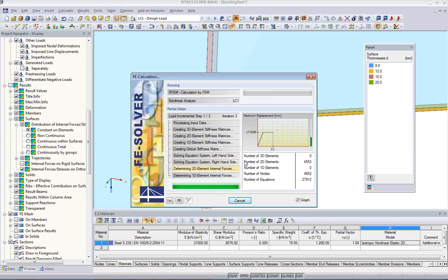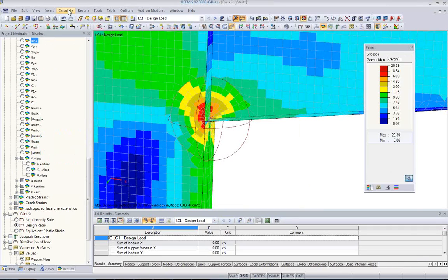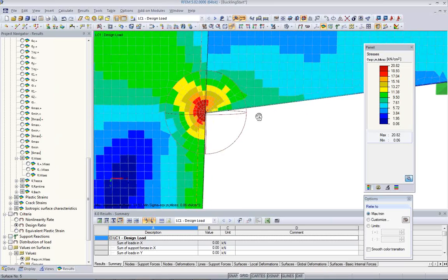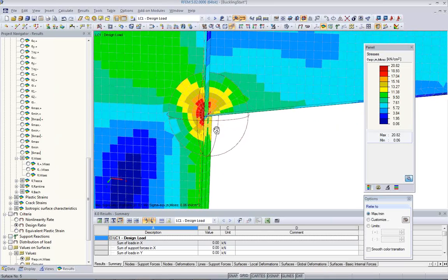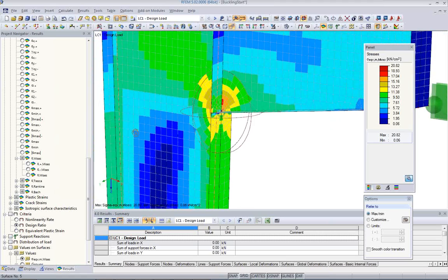Okay, load increments, one more time, I explained already. I have to show you where I can set those options. Those are in the calculation parameters. You can set increments. It's by default, I think, set to 5. If there is problems with convergence, you get a message and you can change it. If not, maybe you can stick with less increments and increase the speed of the calculation this way.